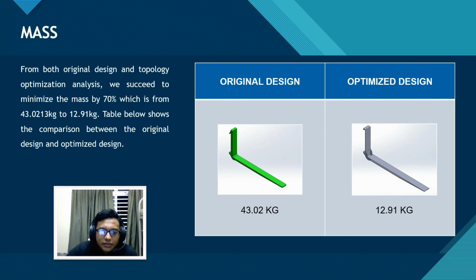First, mass. From the original design to the topology optimization analysis, we succeeded in minimizing the mass by 70%, from 43.02 kg to 12.91 kg.